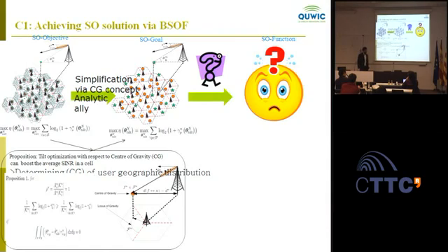But their gamma, I presume, includes the signal to interference and noise ratio. Yes, the gamma. Every user has a dependency on the neighboring base stations, of course. I will come to this. Here the problem is we want to calculate a tilt which optimizes this gamma, using the user distribution in this cell. So your question was, do you need user distribution information for this cell or for all the cells? No, you just need to know the SNR value these users are receiving in this particular cell. And that SNR value will incorporate the interference from other cells.